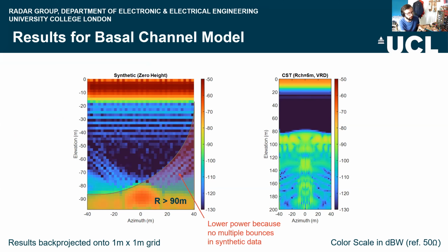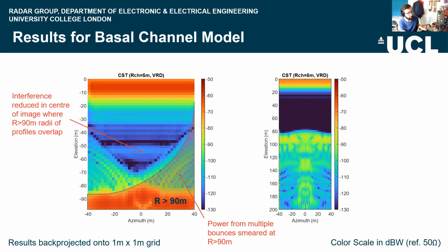So I'm pretty confident that is a result of how we're back projecting these extended range profiles onto the imaging space. And the reason that we don't see that in the center of the image is effectively they're cancelled out by complex summing of all of these back projections for each range profile. So at the center of the image, where most of these arcs would overlay, that's where we're seeing the effect of them being cancelled out, which is ultimately where you get the coherence gain in SAR from.